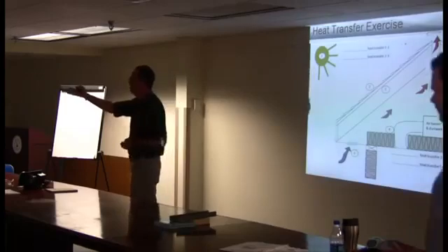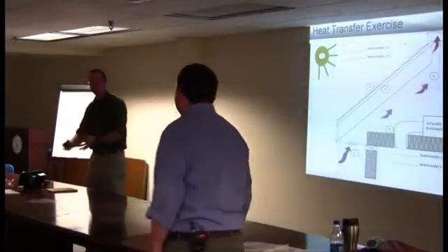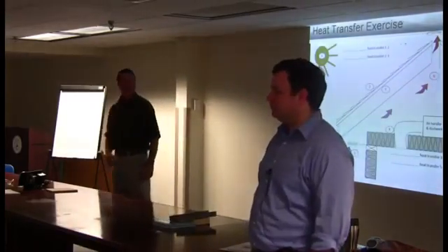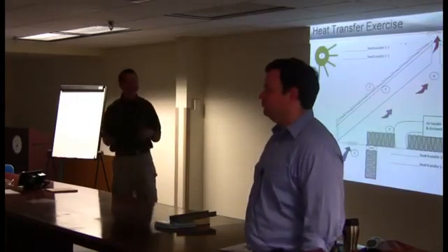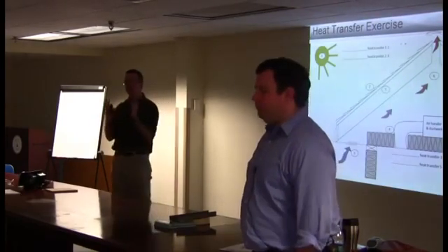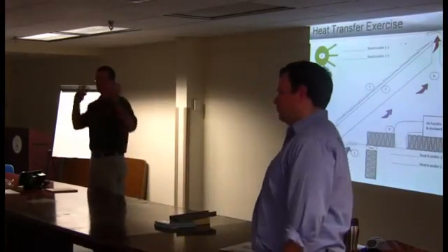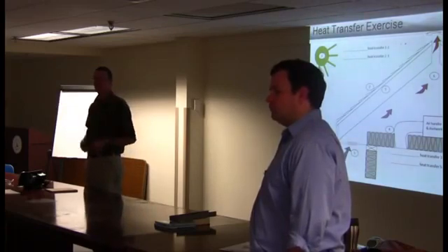Yeah, because that's exactly right. It'll cool the attic for sure, but it'll actually pull air conditioned air from down in here up into the attic, and it's because it's hard to get a perfect air seal across here. So don't use a fan if you're going to vent. But in general, on commercial buildings, I really am going to recommend that you just try to change the envelope so that it's not doing that. That's a general statement. Joe?